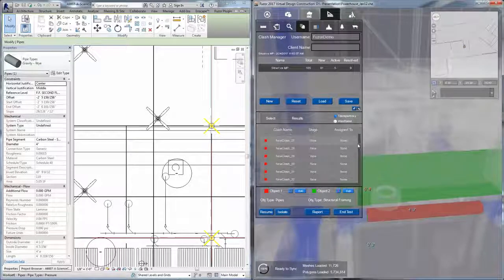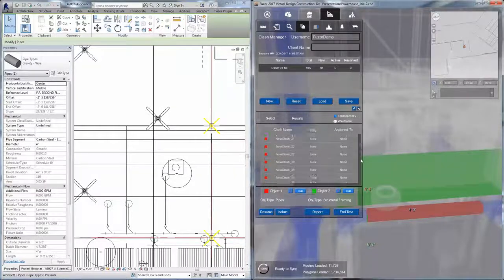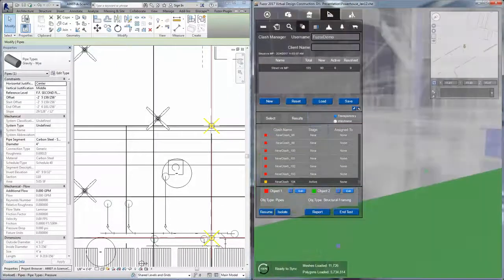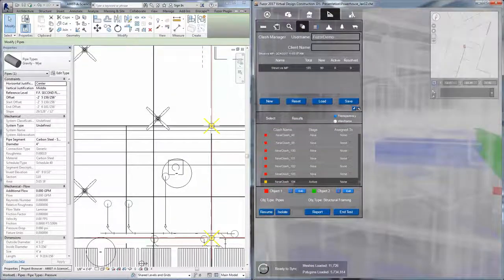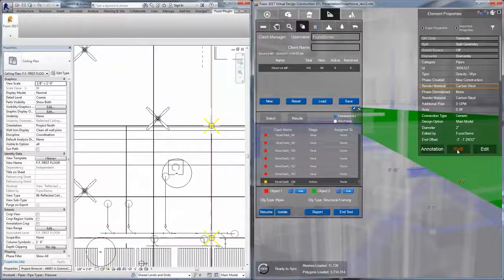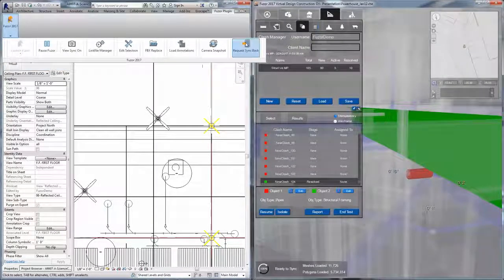Originally we had 104 different clashes. Now it's actually showing 105. So if you do create more clashes, it'll actually tack those on to the end. So since we started at clash 0, this is going to be clash 104 as the 105th clash. And since I moved that entire pipeline over, it's actually showing that this particular pipe is now running into that. So I could always grab that, and again, I can quickly resolve that one, get that out of the way, and then sync that back again.